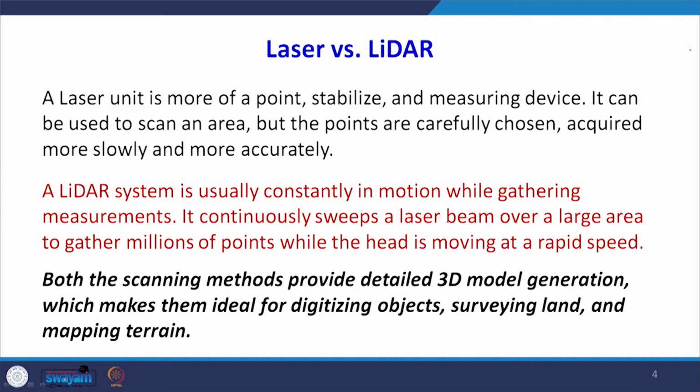Now, we have, for example, the instrument which can measure the distance with a laser beam. So, very small replacement of the tape with the laser based measuring devices are available. We can actually scan some area, we can scan the chosen point, selective points, and the data from these laser based devices is coming out very slowly, but it is quite accurate data because it's a well pointed beam. So, it's accurate data, but it is slow data.